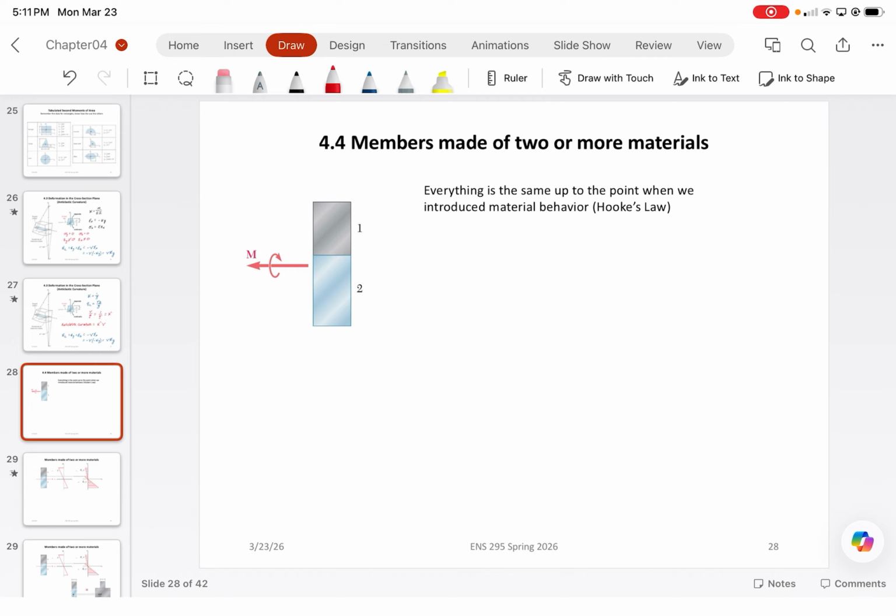Yes and no. Try. The strain is the same? Yes, but in this case, because we're dealing with bending, the strain as a function of y is not exactly the same. But even though the strains can vary in the y cross-section, we still need to apply some variation of compatibility.